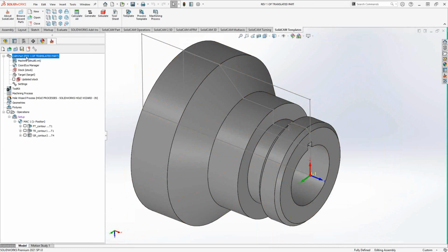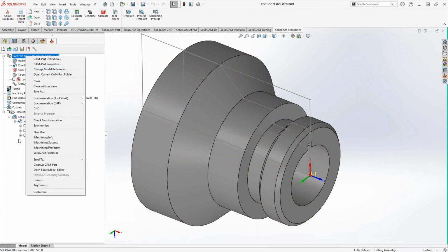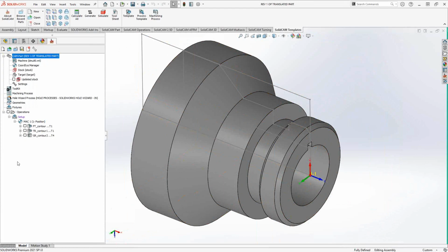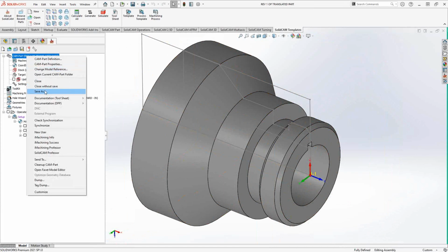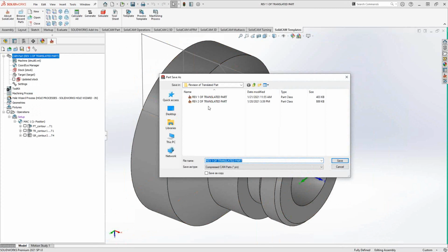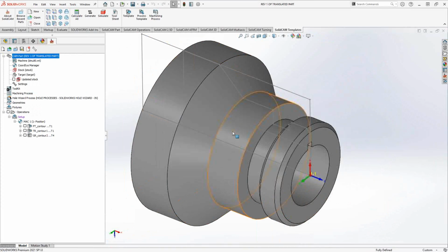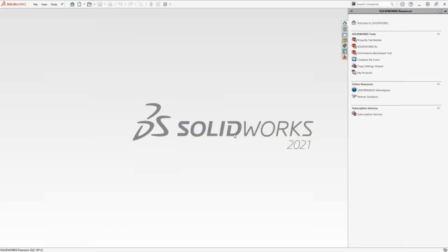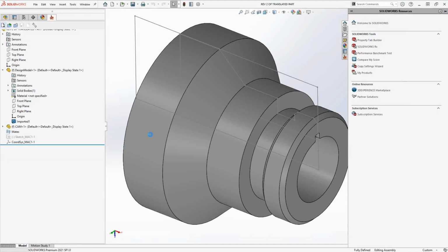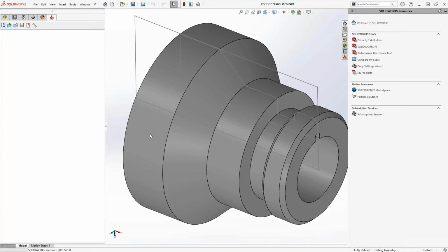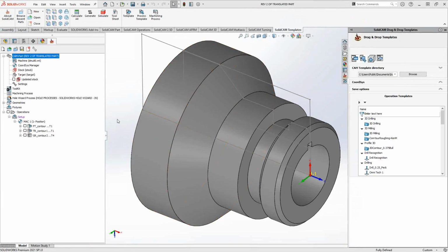So to do the revision, I can't just do a change model reference and then expect everything to be updated, because that's essentially a brand new solid. So what I would recommend doing is still doing the save as, simply because I'd like to call it a Rev2. So in this case, you can see that I've already done this before. Obviously, for these videos, I practiced it ahead of time. So this is the Rev2. You can see that it has the Rev2 name on the top there. It is the same file.